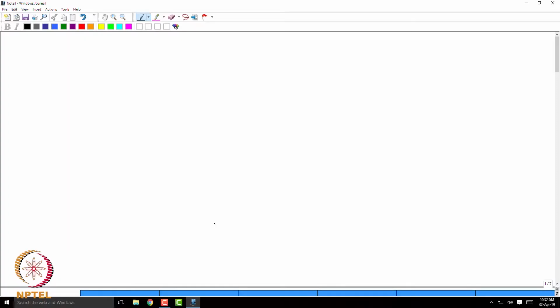Okay, so we are looking at turbulent flow in the pipe. That's what you just did, in fact, right? We calculated V average divided by, or rather V max, which is what is in the numerator, V average. V average by V max is equal to 1 divided by 1 plus 1.3 square root of f.